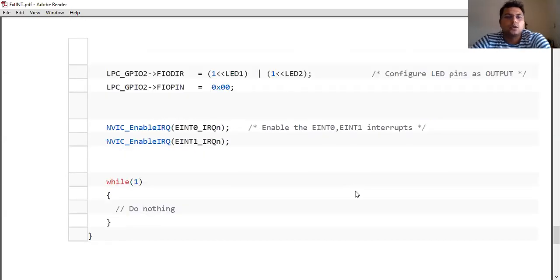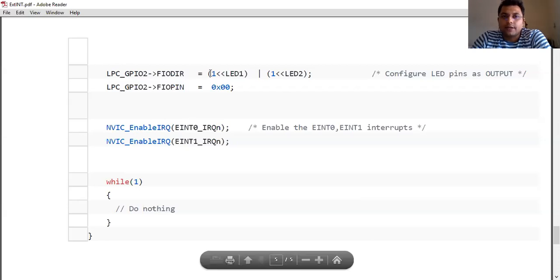Then corresponding to LEDs, because LED pins would be connected to LEDs directly, those pins would be used as output pins, because the system would put the corresponding toggled value over those output pins, and those output pins are connected to LEDs directly.